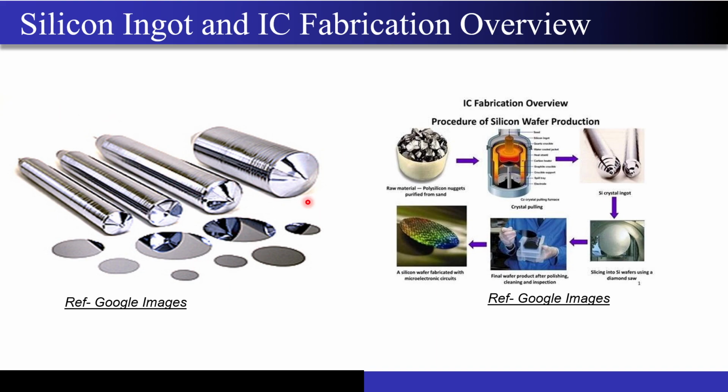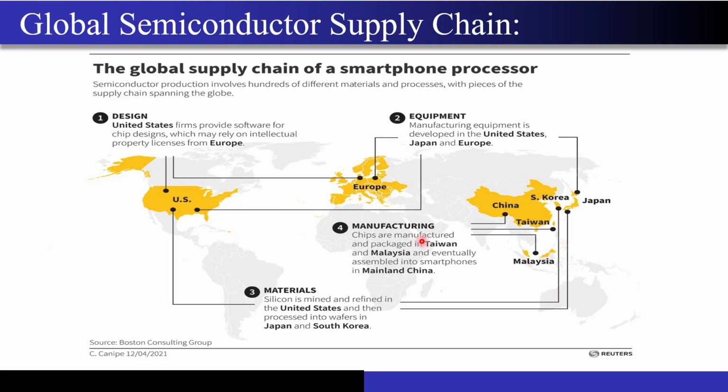Then you slice them and you get wafers like this. On those wafers, the foundry will perform photolithography, etching, ion implantation, every operation, right? And they will make your circuit. And once this wafer is processed in a batch, they will slice it and send the dies to you, correct?